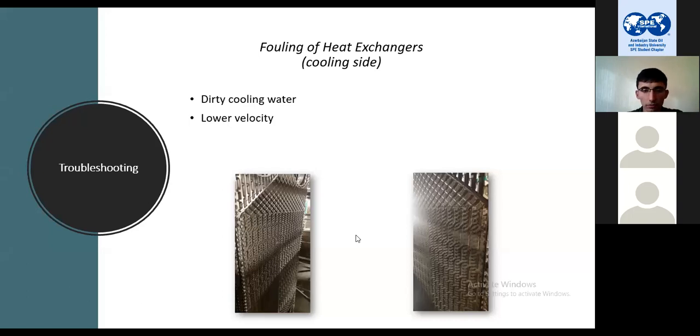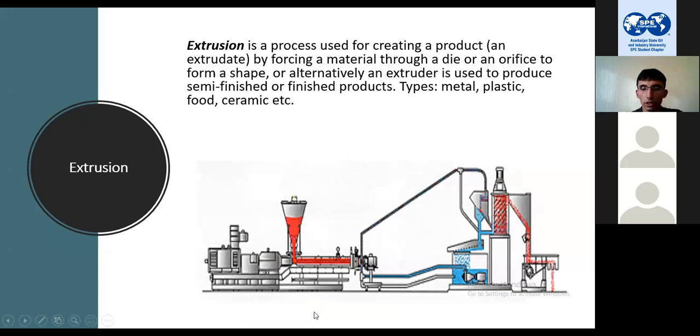Let me show you that photo again. You can see this blue part is water. It's called pellet cutting water. It's used for solidifying the melt, for cutting, and also to transfer pellets for further actions. This water meets high temperature melts and gets heated up, so we have an exchanger, or simply a cooler.